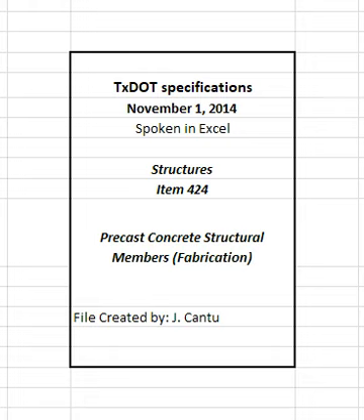Control concrete by compressive strength tests of cylinders or other pertinent performance tests detailed on the plans or pertinent items. Concrete compressive strength test cylinders will be made, cured, and tested in accordance with TEC 704I. Cure release of tension strength cylinders in accordance with TEC 715I when match cure technology is used. High strength concrete, f'c 9000 psi, is accepted based on 56-day compressive strength testing. Concrete design strength test cylinders for high-strength concrete will be made, cured, and tested in accordance with TEC 704I.